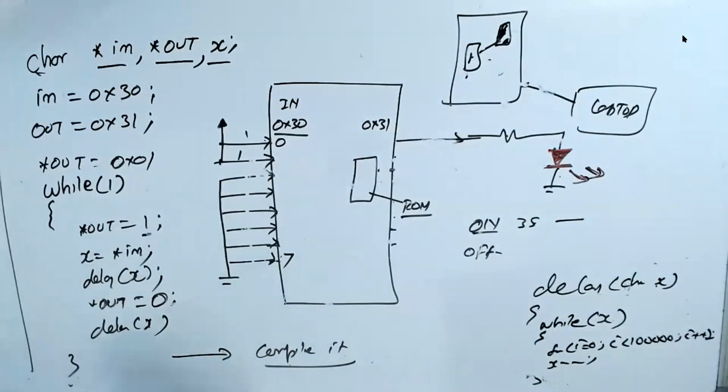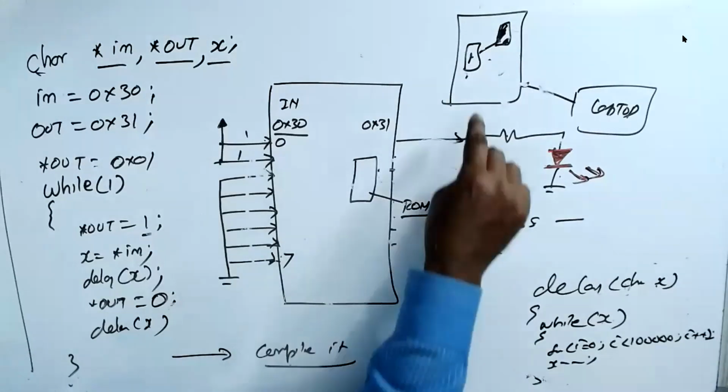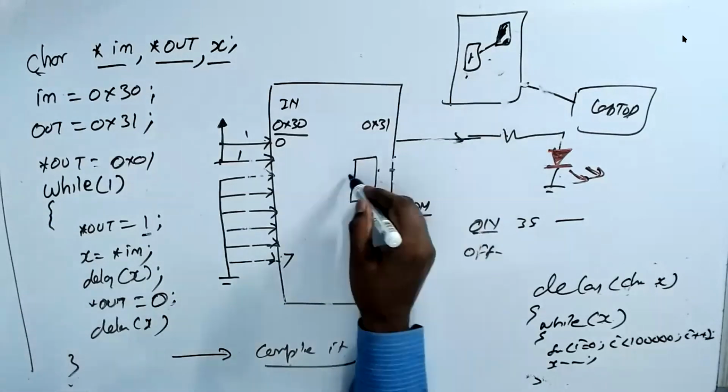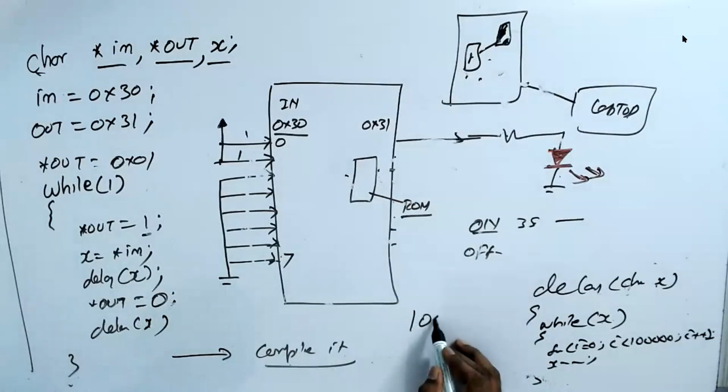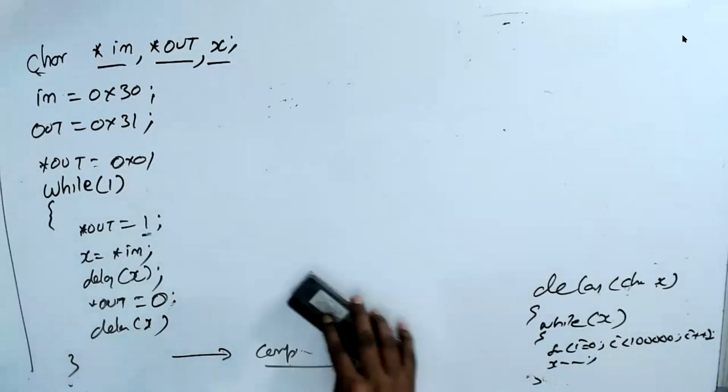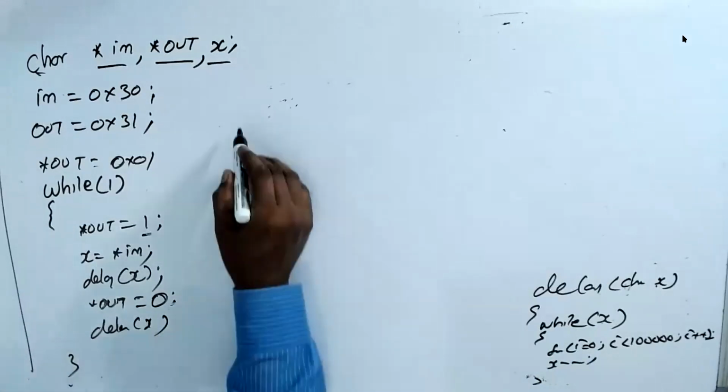That means you cannot copy the same IC to one more. It's not possible. This is called a security fuse. If you blow the security fuse, nobody can read the ROM. So what I do is I make about 100 ICs. I buy 100 microcontrollers, program everything here and sell them to the market. For you, the advantage is you buy my IC. You have a microcontroller.